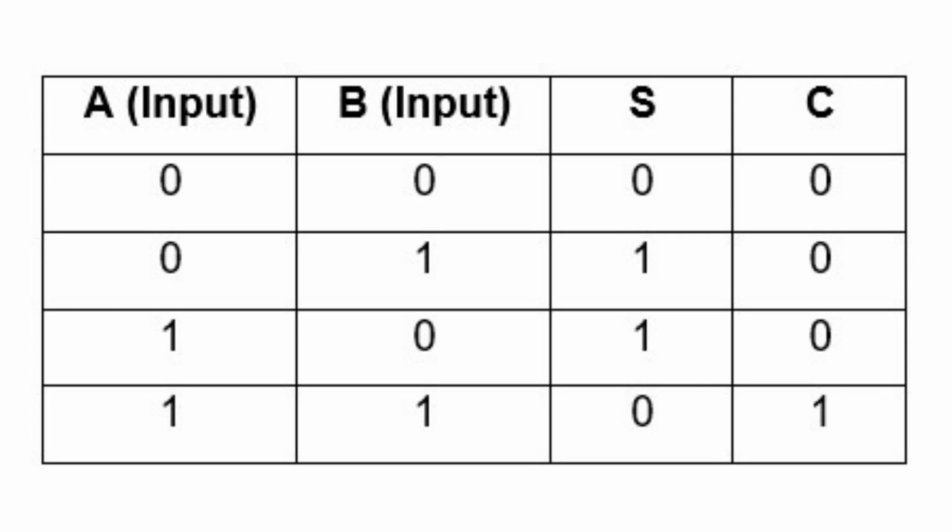The table for this part shows that we have two outputs, namely the sum, which is represented by the letter S, and the carry, which is represented by the letter C. Both outputs S and C have values of 0 if both inputs are 0. Output S is then observed to have a value of 1 whenever the two inputs are not alike, and a value of 1 for the output C whenever both inputs have values of 1.